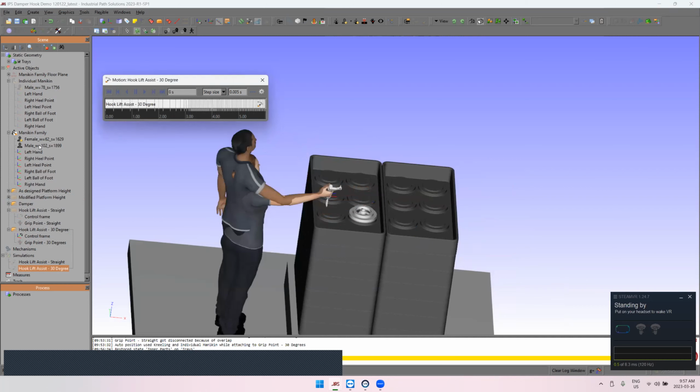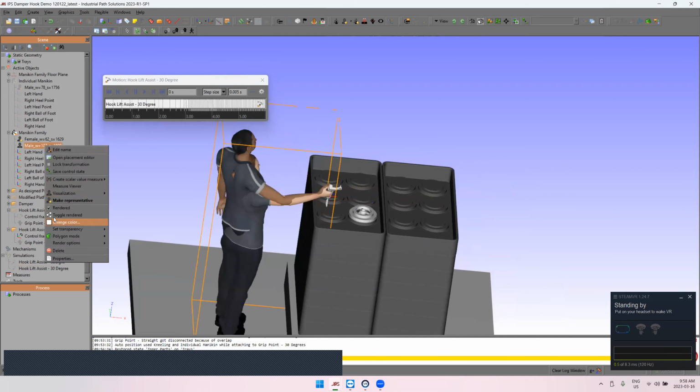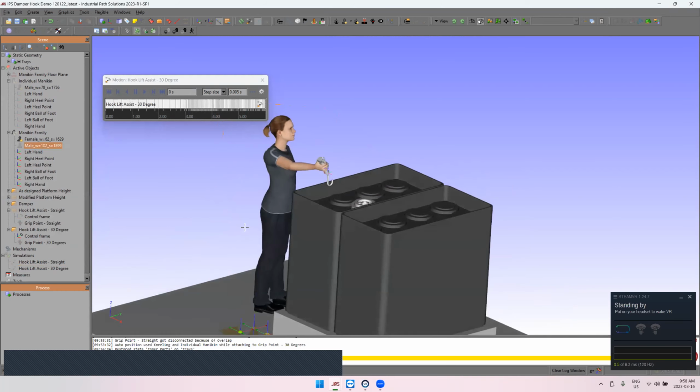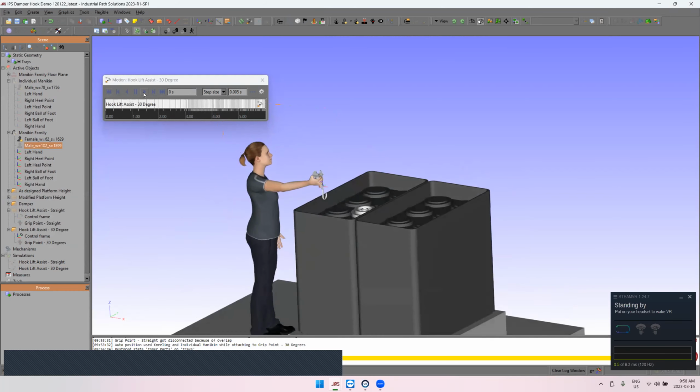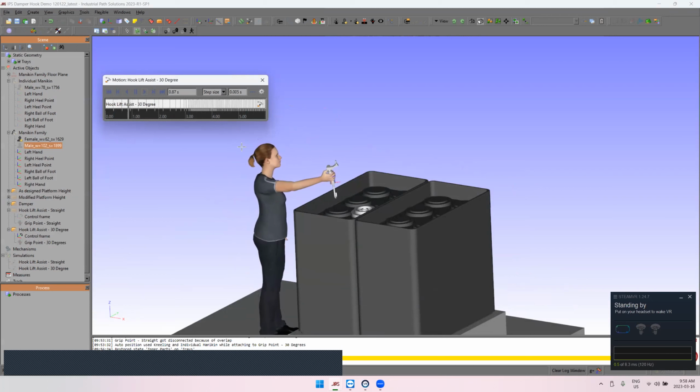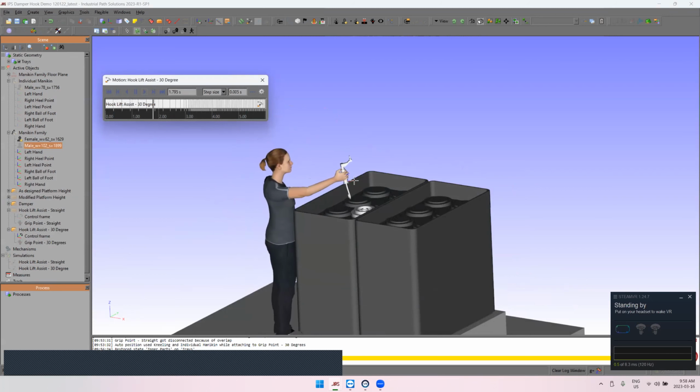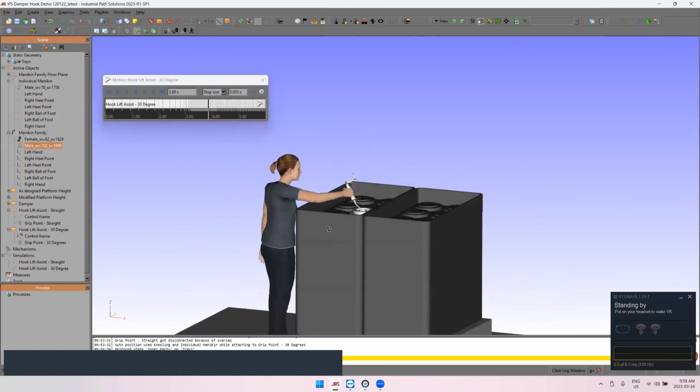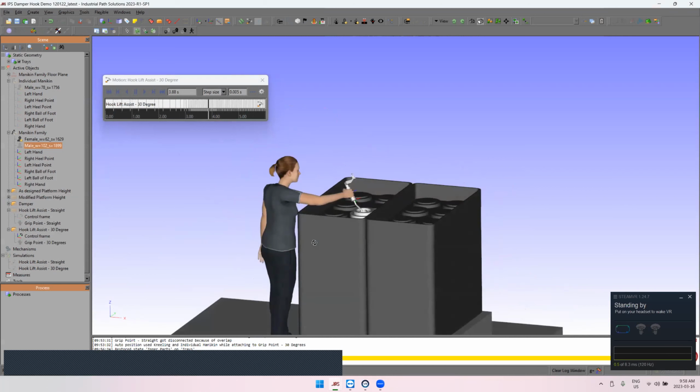I'm just going to review this one more time, and this time I'm going to de-render the male mannequin and observe the shorter female here. When looking at the shorter female, we notice that the hand is above the shoulder, which could be a potential risk for ergonomics. So we're going to pause there when they're just starting to engage it, and we can look even before that when their arm is elevated higher. And we can perform a postural analysis on that aspect as well.